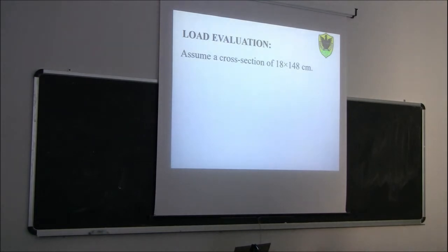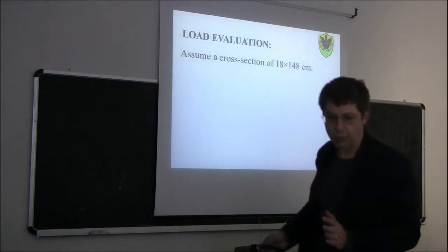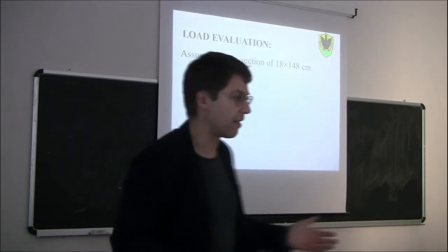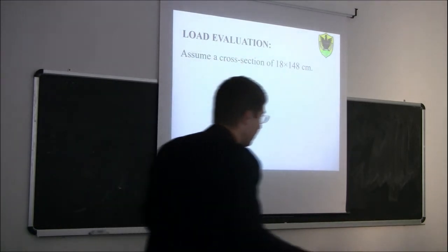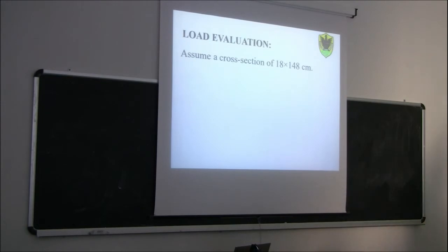I mean, you can also find trees which are 100 meters high, you know, the sequoia trees in Canada. Of course, you can't really use them for a structural purpose because of the trapezoidal shape anyway. Nowadays, when you exceed probably 5 to 6 meters, the only way is to use engineered wood products, so either LVL, laminated veneer lumber, or glue laminated timber.